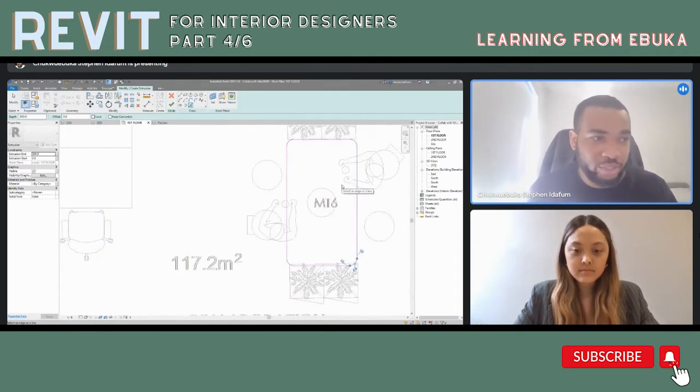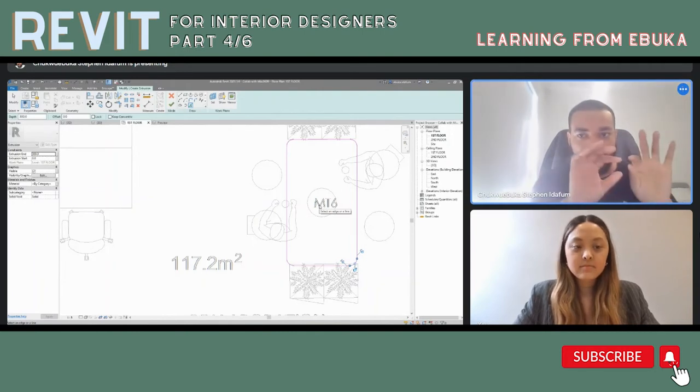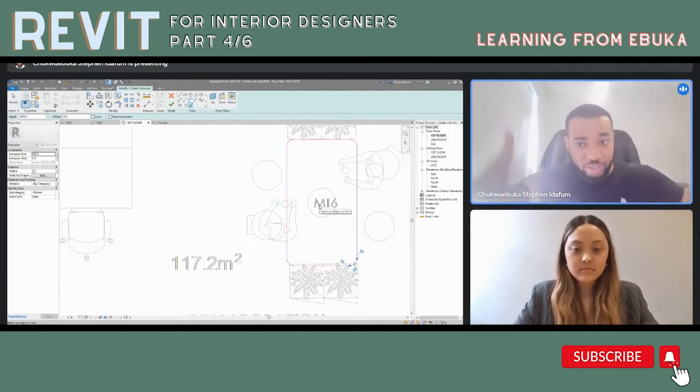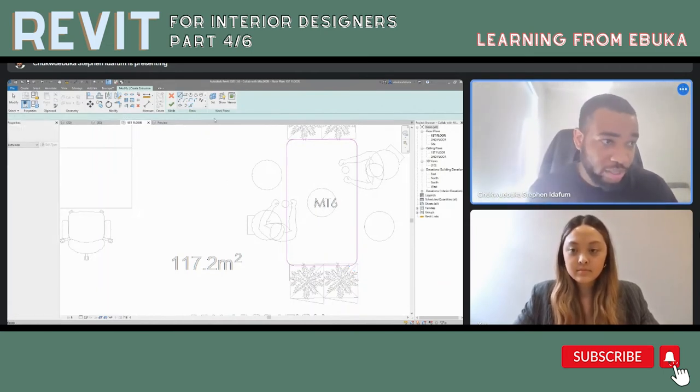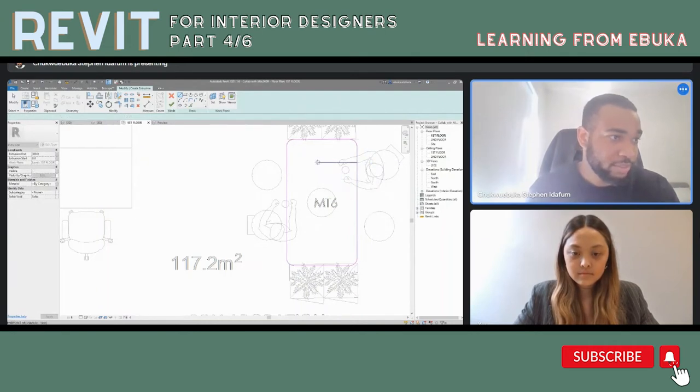We know that there's going to be a hole here, because you need to put the other parts and your desktop to rest on. So we're going to create lines in there as well. I'm just going to get something that looks like this, and I'll press CO for copy. I'll copy to this other side as well.